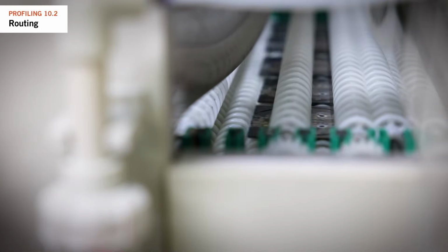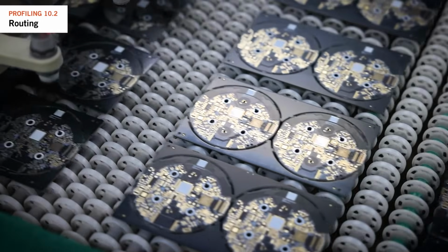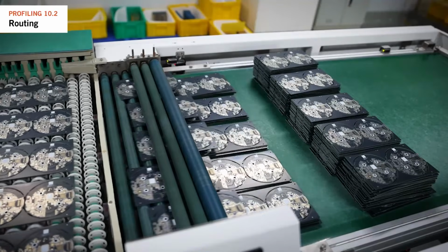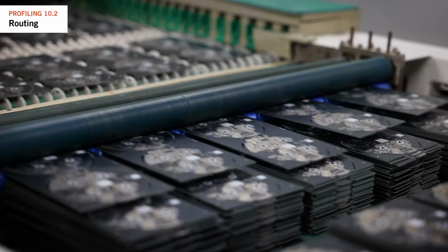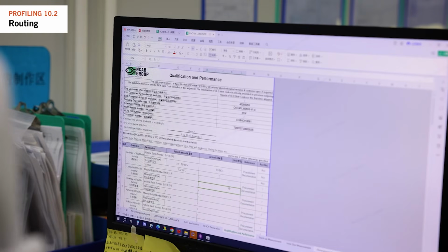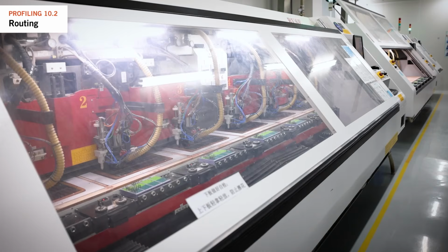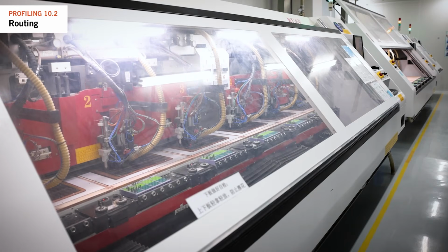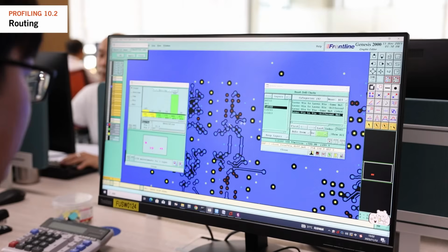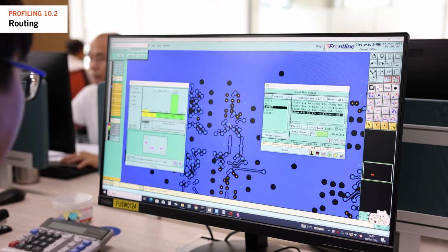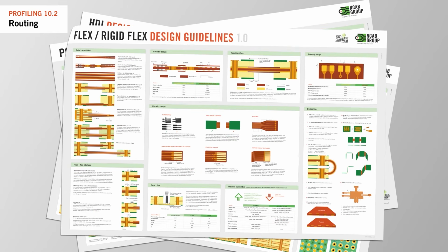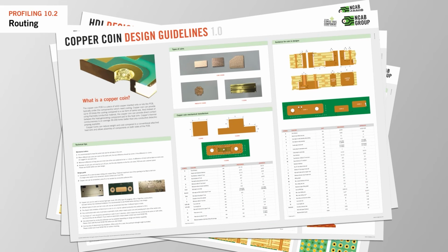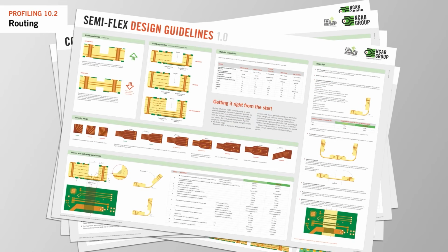Our PCB specification shows the minimum tolerances that shall be applied, but if a customer requires tighter tolerances, we follow those. The results are defined in our Certificate of Conformity. We only use approved routing machines for NCAB products. Additionally, we support customers' PCB designers with detailed design guidelines, specifying tolerances for PCB profile, holes, and other crucial elements.